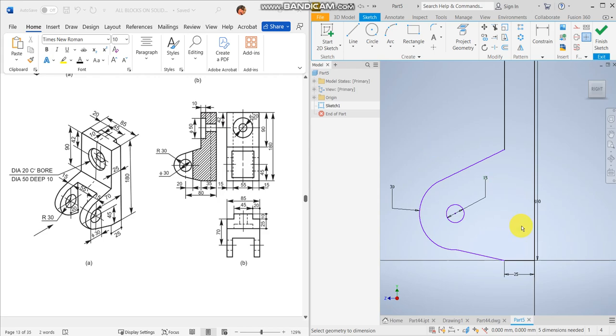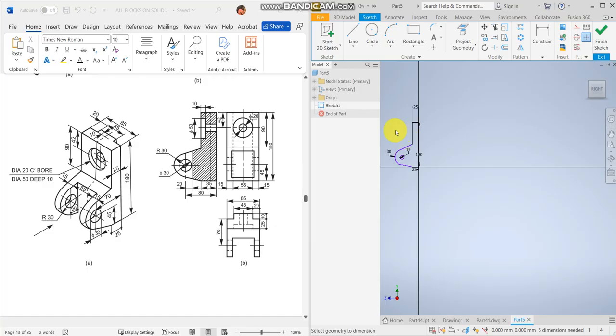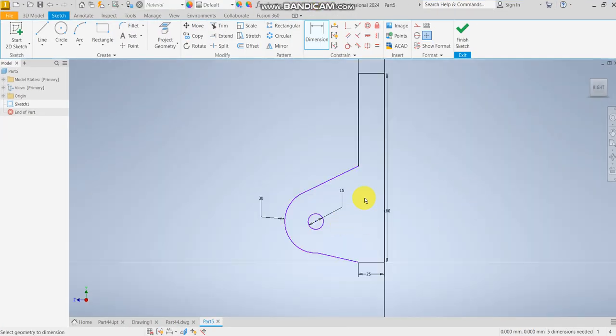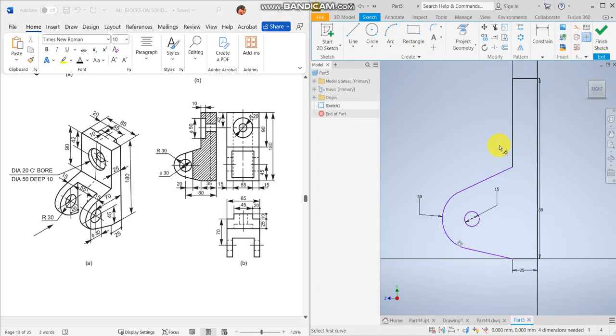Then what is the next distance? Since it's properly dimensioned, let's see how we can get the distance. There's a little work we need to do now. We need to understand how this sketch was done. Let me see if I can make the constraints. Watch please. I come to this area, tangent from here to here. So we have something as smooth as this now. But let's see how we need to get the dimensions correctly. The small dimension from here to here will be 70.